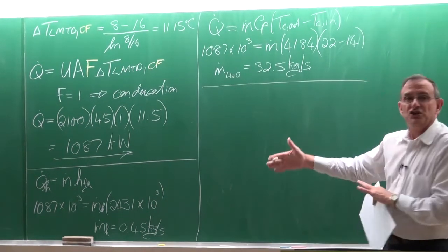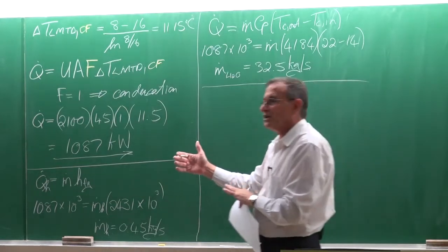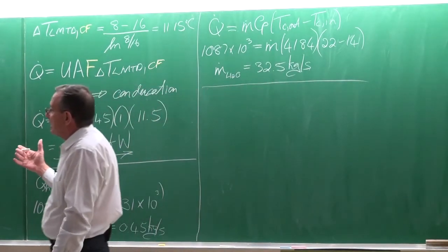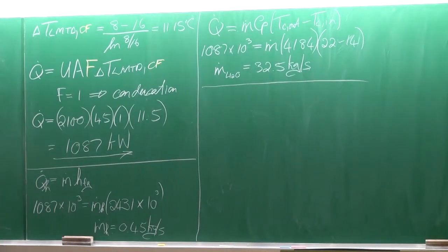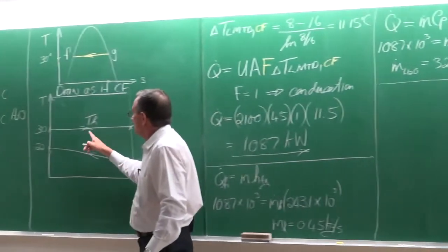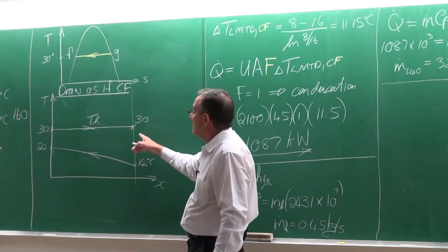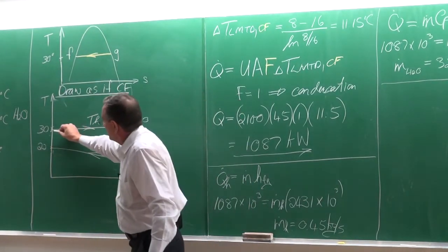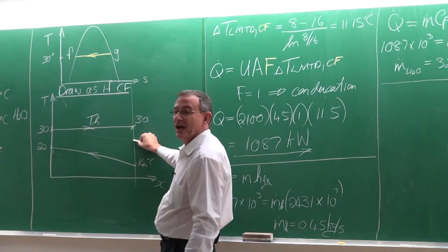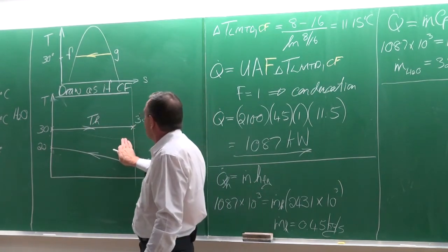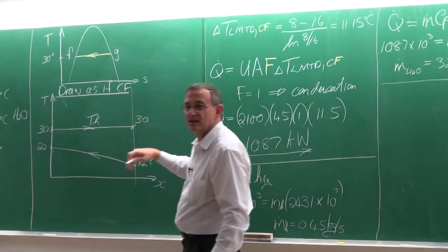I've previously mentioned how important it is in heat exchangers, that the best type of heat exchangers are normally when you've got a phase change. And what this now illustrates are two things. The one is, as I've mentioned before, your temperature remains constant. If it wasn't a phase change fluid, then this temperature would have to do something like that, so your delta T would be lower. Okay, that's the first thing.